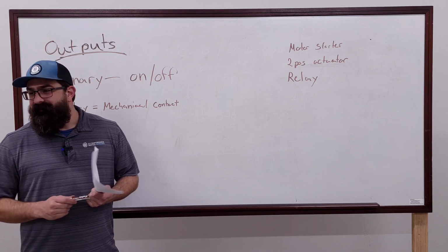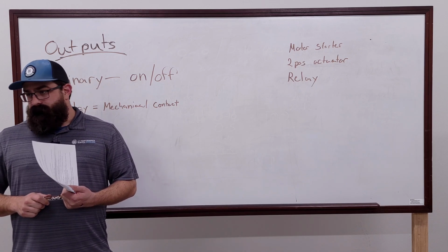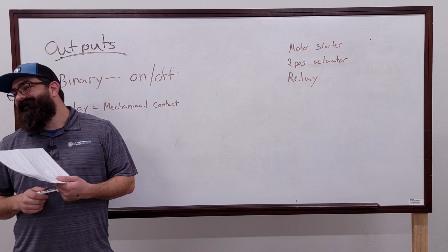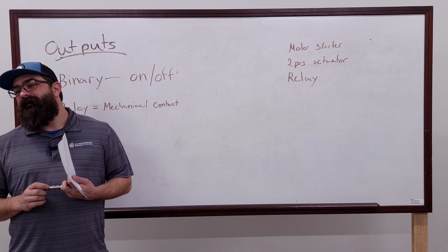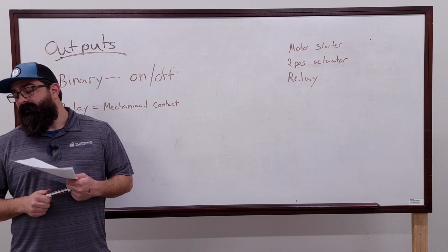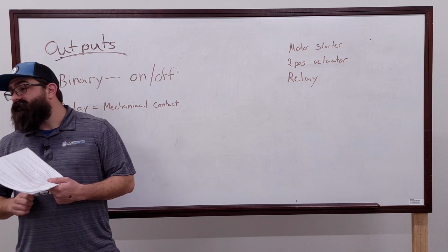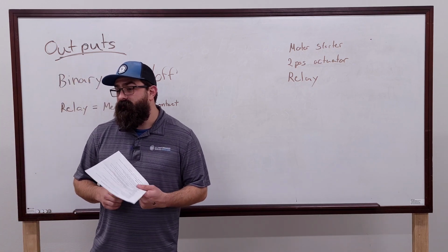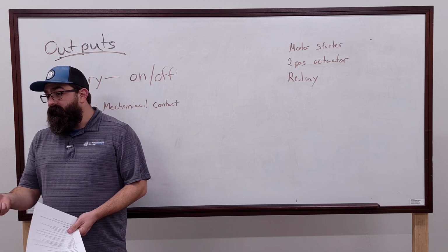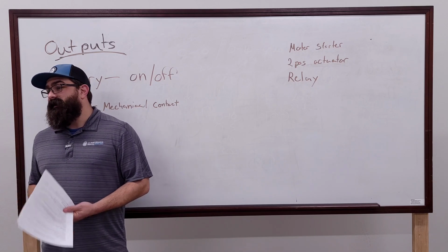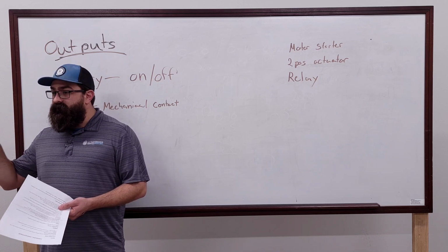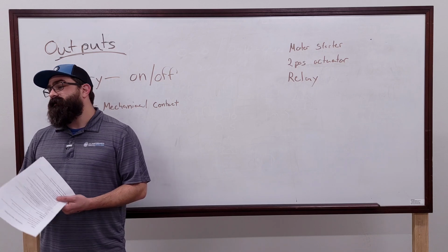Are the HVAC controllers Triacs? Which one? PCB 1630, 1620? I don't know what label is over it. Okay. Some of them are, some are not. You have to look at the actual controller, and then some controllers have a mixture. So like an ECB 203 has triacs and relays on it. The first 6 outputs are relays. The other 3 are called universal outputs. They're UOs. Those are triacs.